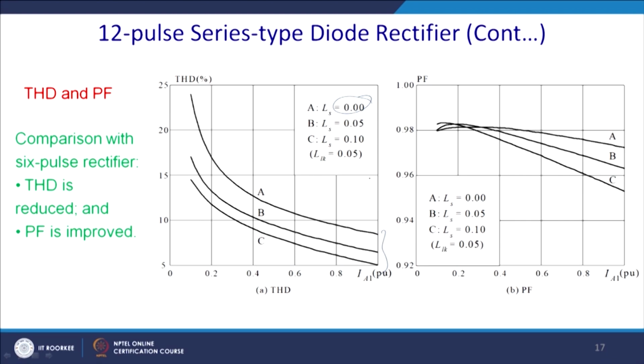If you have a little more source inductance of 0.5, it will come to around 6%, and generally it is present, and thus you almost get into the 5% standard. If you add around 5% inductance, you can go well above the requirement.